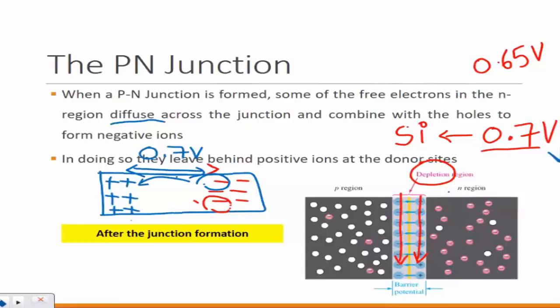What about static electricity? They may not damage these, that's only a little bit, but they may damage some ICs. These won't get affected by the static a lot. But static usually affects more sensitive devices. ICs can be more affected by the static electric field, unless some circuits have ESD, electrostatic discharge terminals, so we can discharge, or some bands that you can wear.